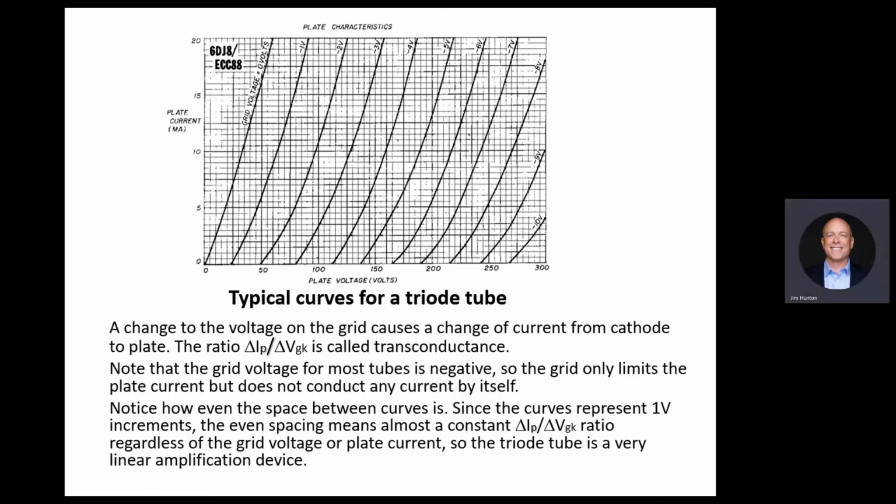And that is true in a diode, pentode, or triode. That's always the case. So the plate voltage tries to pull those electrons, and the amplification is achieved by repelling them. How do we repel them? We put negative voltage on a grid that's between the plate and the cathode. Now, the more negative, the more repulsion. So it's actually like a reverse effect of what we think about amplification. We're not amplifying, we're lowering the amplification. If you let it go without a grid, it will be the maximum current. It'll be basically here.